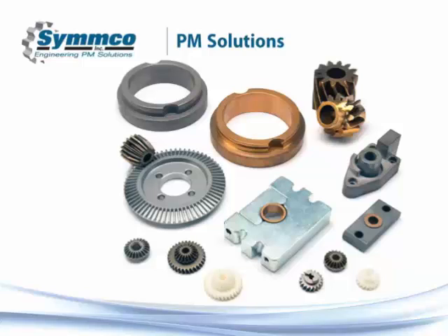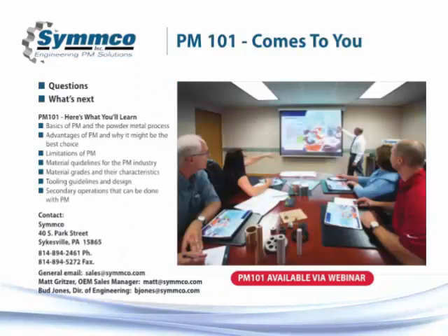Okay, and it looks like we have one more question and a few more minutes here. What is the maximum level part that you can press? Oh, that's a good question. Depending on the tonnage ranges, and again, we have multi-level presses in 60-ton, 150-ton, 200-ton, and 400-ton, where we can make 3 bottoms and 2 tops very easily. We can add a 4th bottom level using maybe a core rod or a die, which is a fixed fill die, common in the industry. So at this point, depending on tonnage, I'm going to say 4 bottoms and at least 2, if not 3 tops, depending on the part complexity.